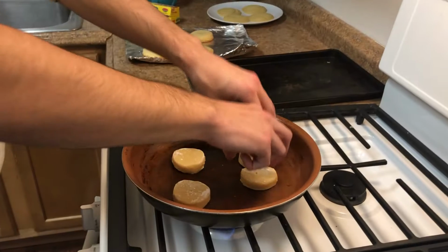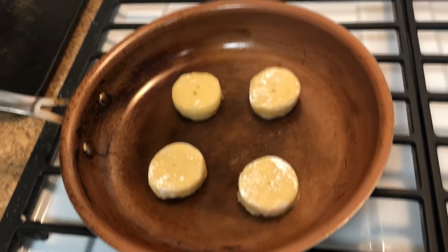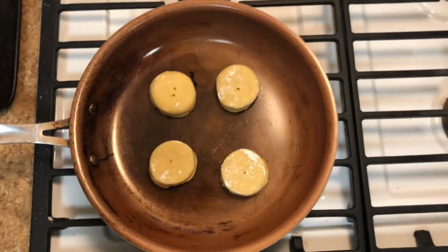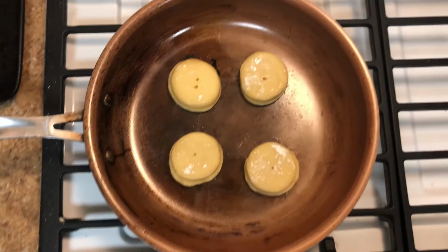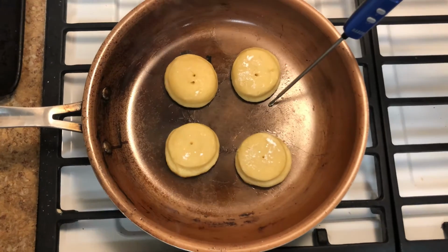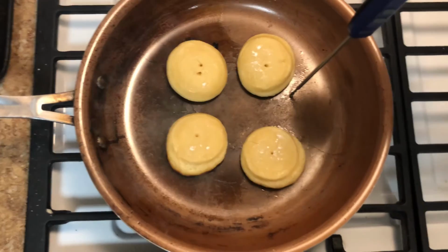On the stovetop, a natural gas flame heats the bottom of the skillet via conduction, convection, and radiation. The heat transferred to the bottom of the pan flows through it via conduction and then flows through the cookie via conduction, cooking it. The pan and cookie also transfer heat to the air at their surfaces by natural convection, which we will neglect for the experiment.